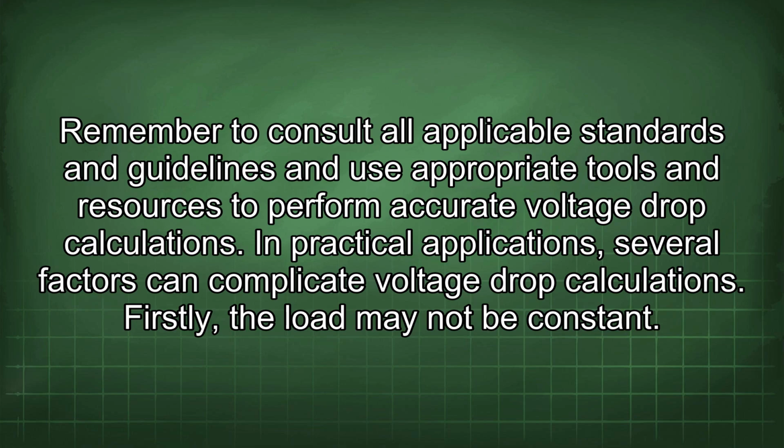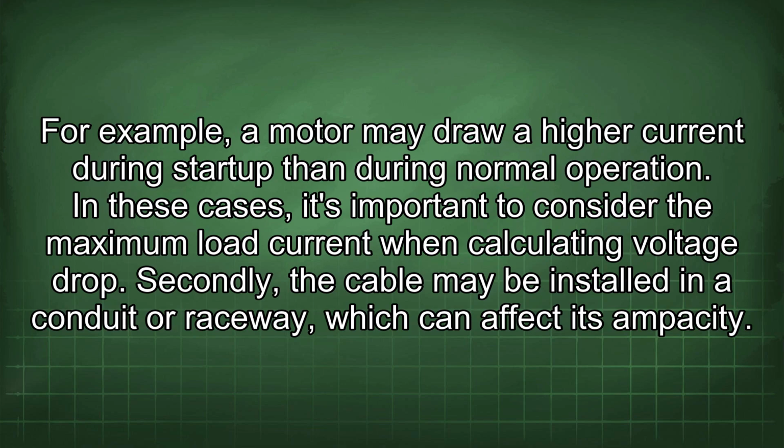In practical applications, several factors can complicate voltage drop calculations. Firstly, the load may not be constant. For example, a motor may draw a higher current during startup than during normal operation. In these cases, it's important to consider the maximum load current when calculating voltage drop.